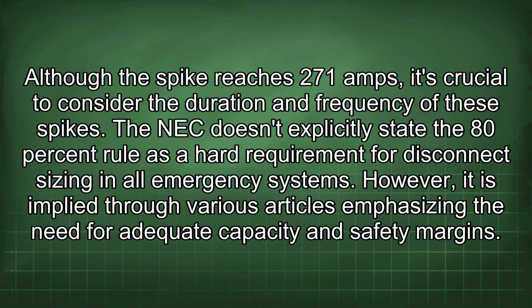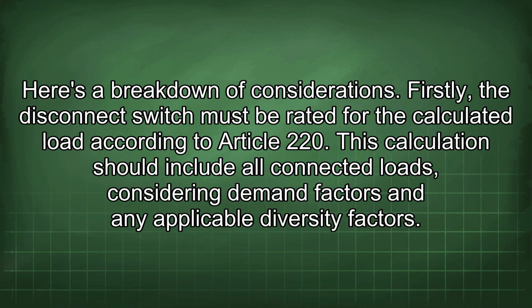The NEC doesn't explicitly state the 80% rule as a hard requirement for disconnect sizing in all emergency systems. However, it is implied through various articles emphasizing the need for adequate capacity and safety margins. Here is a breakdown of considerations. Firstly, the disconnect switch must be rated for the calculated load according to Article 220. This calculation should include all connected loads, considering demand factors and any applicable diversity factors.